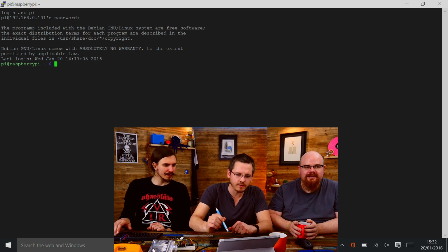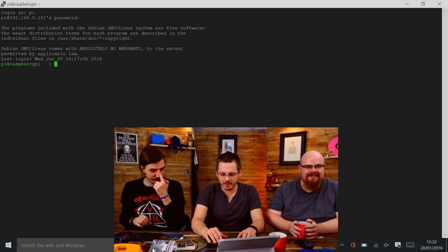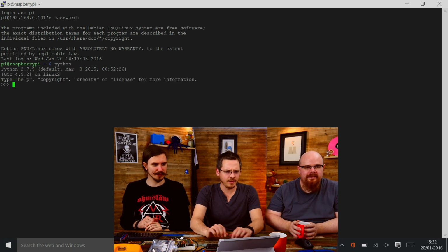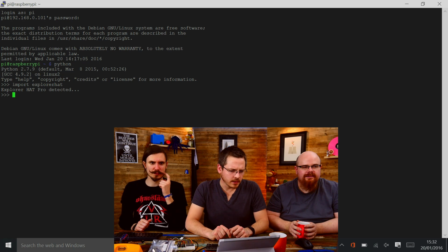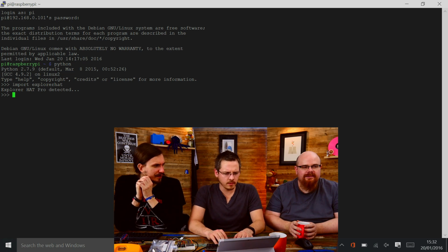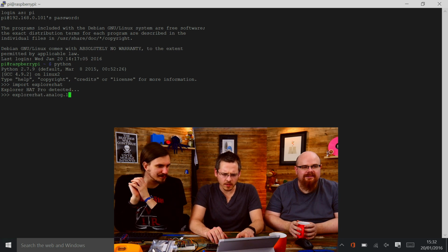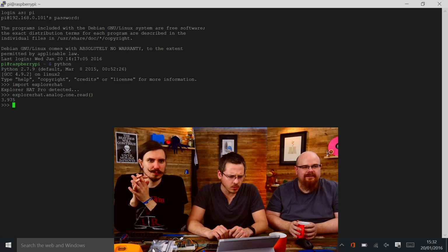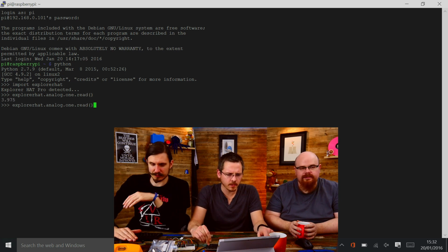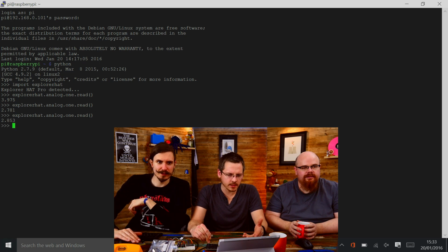I've got your Pi over here. Oh, in your Pi. Aha! You just type python. All right. And then import explorerhat. And then read me an analog value of explorerhat.analog.one.read. Boom. Oh, there we go. 3.975 volts. Let's cover it over. 2.78. See, that's how easy it is.